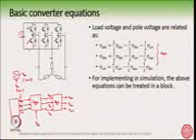I get this SA, SB, SC from the comparison. Here I will have the triangle, and I will have the VA star, VB star, VC star. So here is the comparison. As we have already seen earlier, if the modulating wave VA star is more than the triangle, then you turn on the upper switch, otherwise you turn on the lower switch. This is how the whole logic is developed.